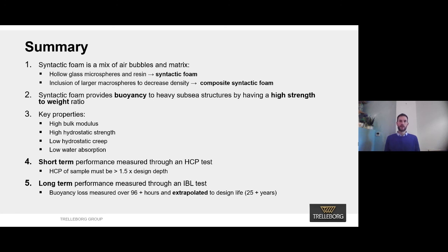And then we talked about key properties of syntactic foam here at Trelleborg Offshore, and those are things such as a high bulk modulus, high hydrostatic strength, low hydrostatic creep, and low water absorption. And then finally talked about the testing we do at Trelleborg Offshore to ensure product quality. And these are tests such as short-term tests, like a HCP or hydrostatic crush pressure test, and then also long-term tests, such as an IBL test to assess buoyancy loss at the end of the service life.